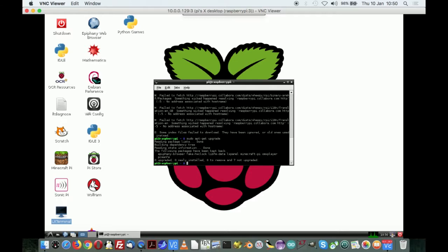So the only options left are changing the spidev library, SPI dev library, and rebooting the Raspberry Pi. I think I will first reboot the Raspberry to see if that keeps it working for one time again, and then see for SPI dev.